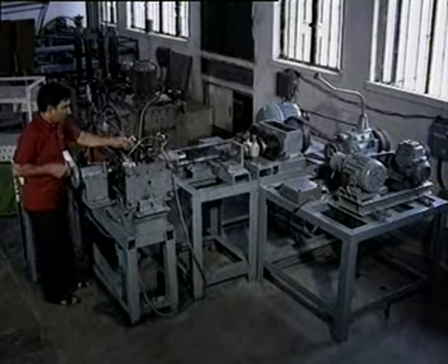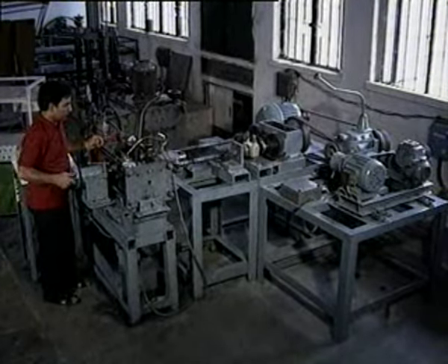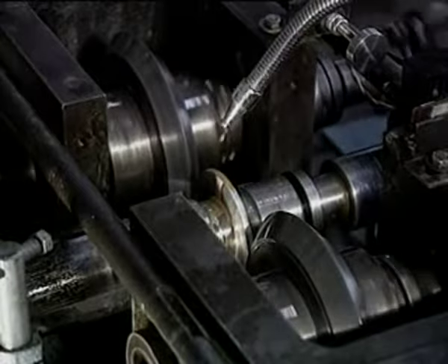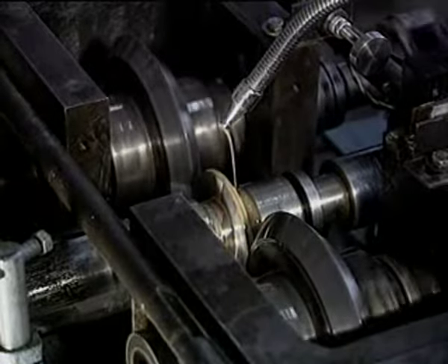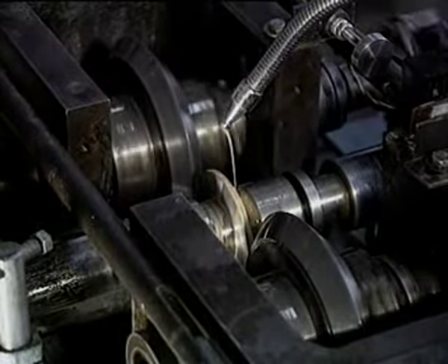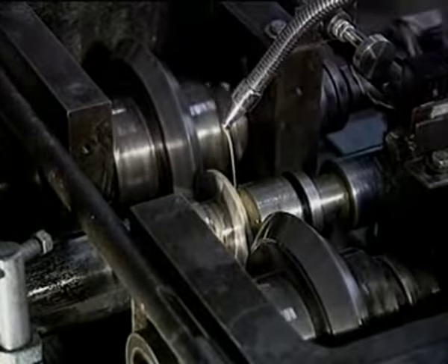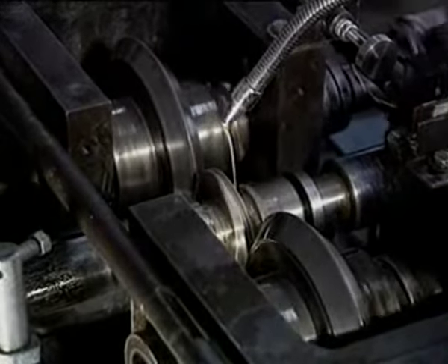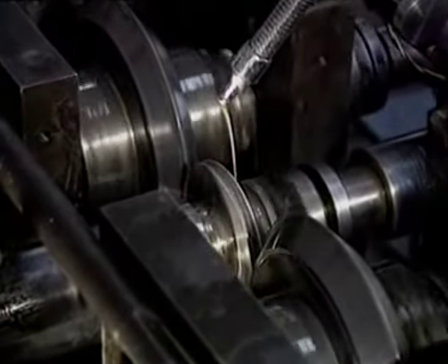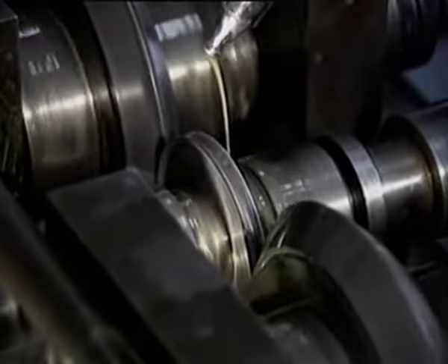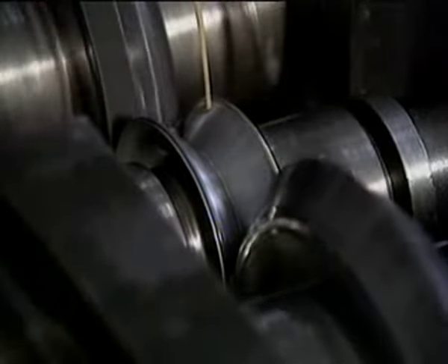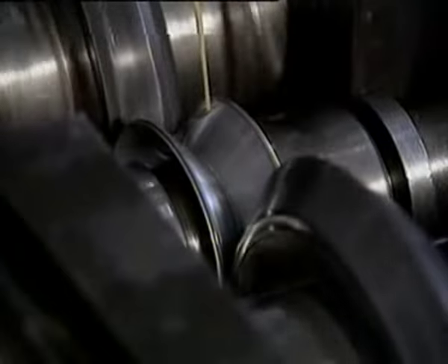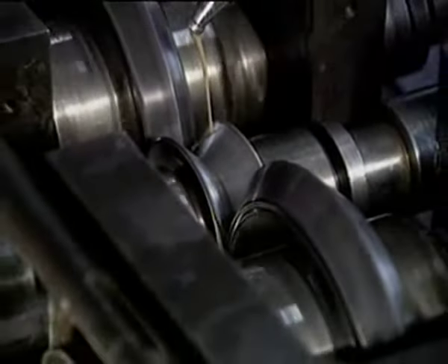This machine can roll circular discs of aluminium, mild steel, and alloy steel of varying thickness and diameters. The two forming rolls are mounted on the spindles running in the bearing housings of the two blocks, one on either side of the job, and these blocks are moving in the dovetail slides of the main bed. In this process there is less material wastage, higher production rate and long tool life. Hence, it is much cheaper a process than any other conventional process.